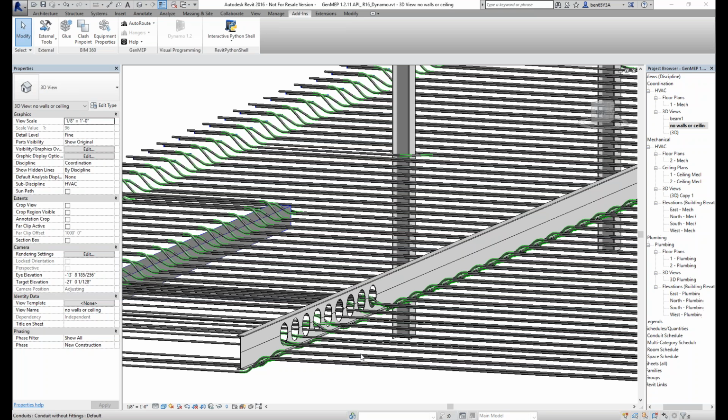Yeah, so at the moment, we do need the actual conduit or pipe or duct as drawn in as a piece of that system. We are working on adding a connector, as in routing from a JBox to a panel directly. We are working on that kind of feature, but at the moment we would need you to draw a little piece of conduit sticking out of the JBox and a little piece of conduit sticking out of the panel.